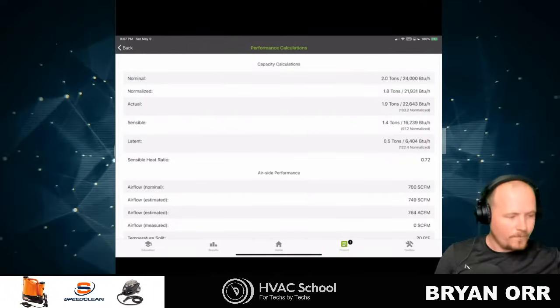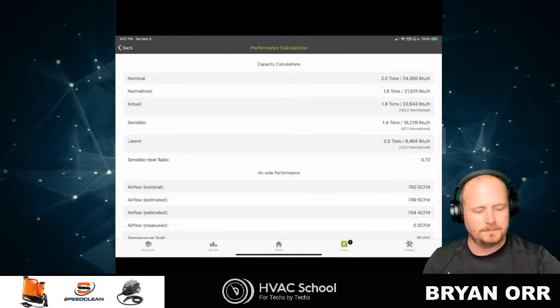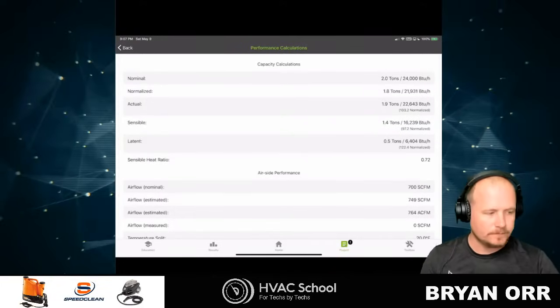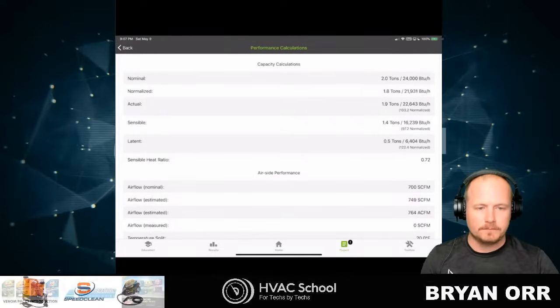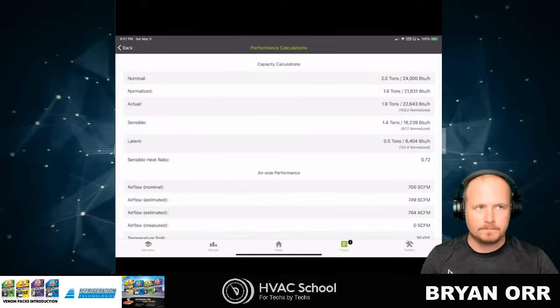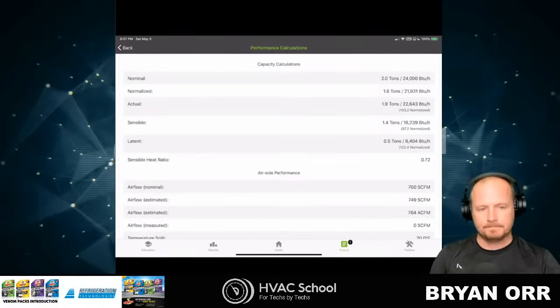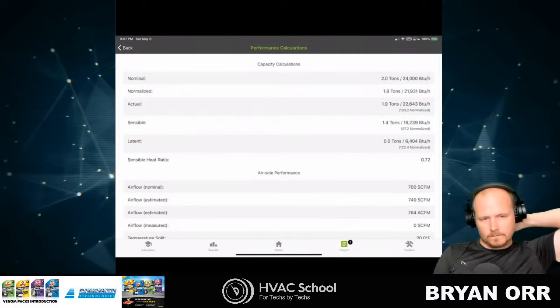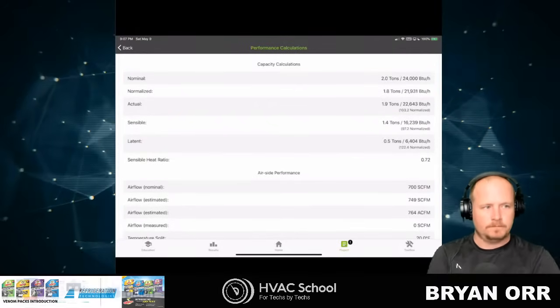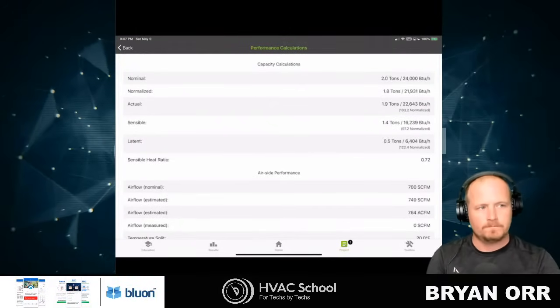So nominal just means normal. If you say a nominal 2 tons, that'd be 24,000 BTUs. But the key thing is that a 24,000 BTU unit really never does 24,000 BTUs of cooling, because it's very rarely at AHRI conditions. So what we do is we normalize the capacity.